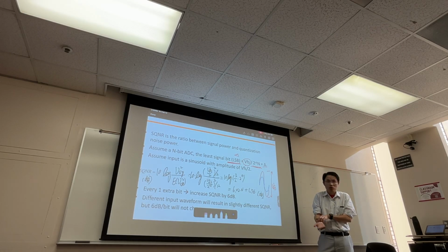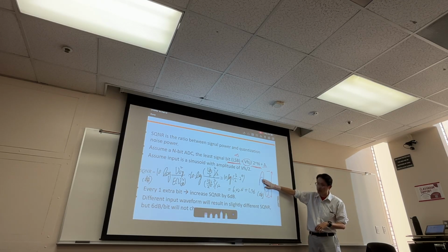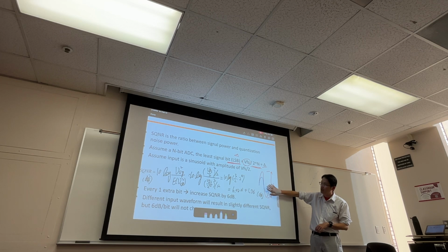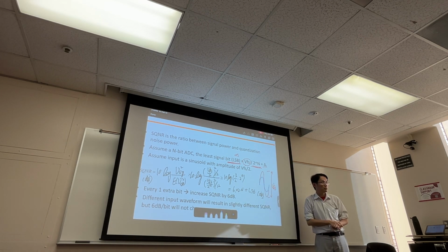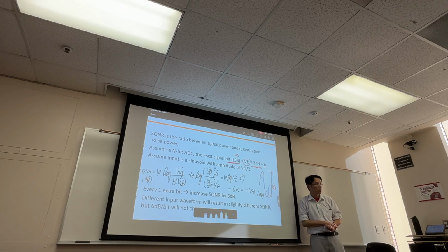At times, your input can become smaller. Of course, it's possible, right? Even the human speech, right? Sometimes I can just voice out, sometimes I can just whisper. I can whisper, right? So then my signal swing becomes smaller. So if I whisper, the signal is smaller, then your SNR, or SQNR at that point, will go down for sure, right? It will go down for sure.